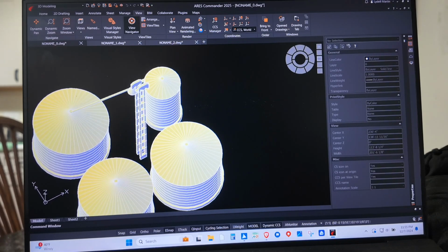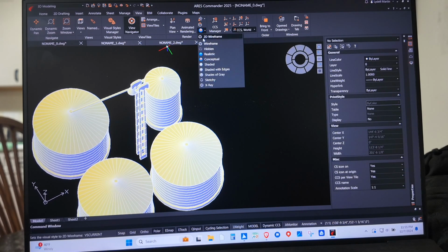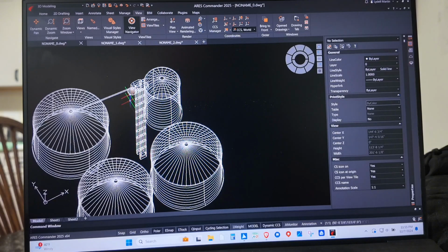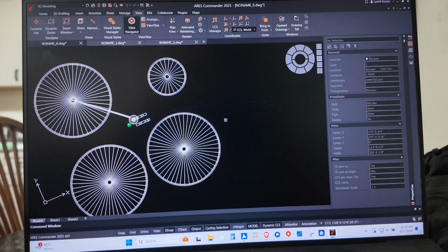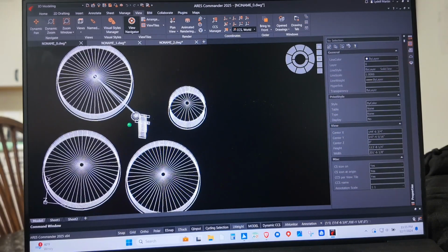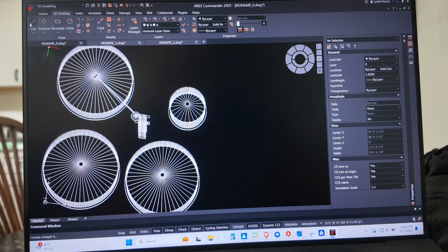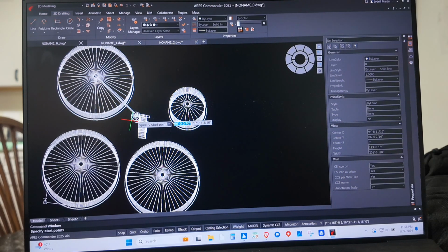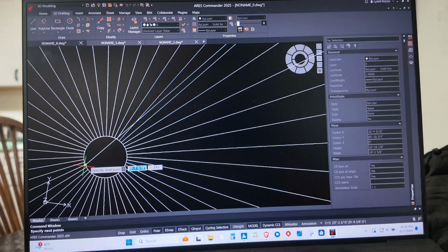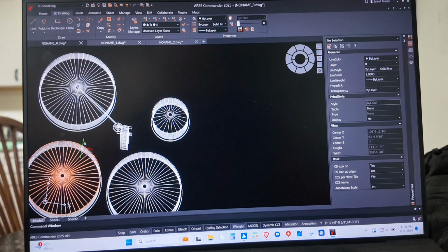So I'll show you it once again on the next spout how to do that because I zipped through it pretty fast. Let's get this pivoted to a nice spot. So like that, we go to 2D drafting, select line, select the distributor where we want to hook on the distributor, come down here, select the far side of this bin opening. That's 65 foot 7 inches. So we're going to do a 66 foot spout again.